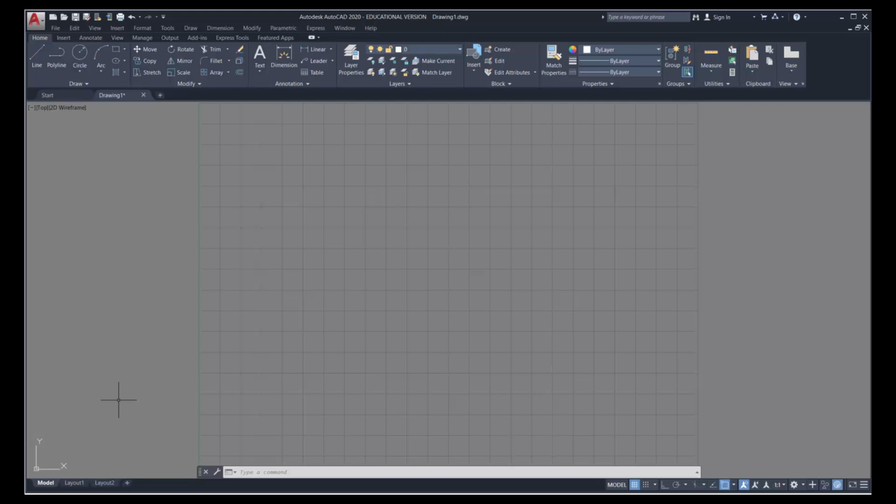So let's start this drawing. Take a look at your PDF file, and you'll notice that I have a start point of 2, 2. So in order to draw a line, we're going to start with the line command. So we go up into the draw menu, click on line in the ribbon at the top of our screen. And this time, instead of clicking on the screen, we simply type in 2, 2 and press enter. And you'll notice it places a point of a line.